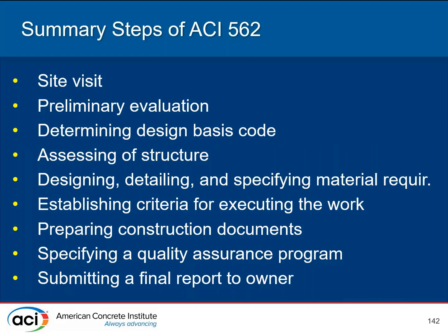So just to summarize, to bring this to the end, here's the list of the steps. You need to do site visit, preliminary evaluation, design basics and code, your more detailed evaluation, the design and detailing, specifying the material requirements from both a structural viewpoint and a durability viewpoint. Get your construction documents together that communicate all this to the contractor, develop your quality assurance program, and at the end of the day, submit this to the owner.